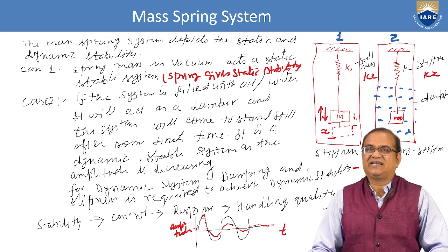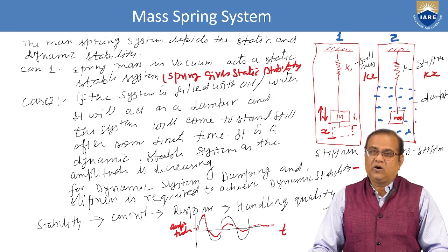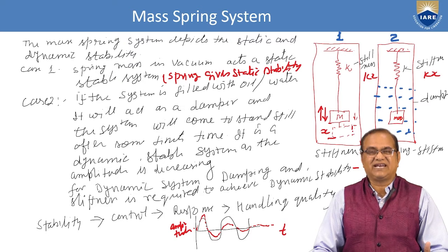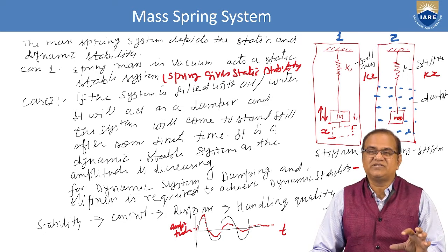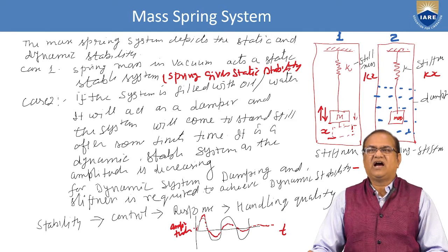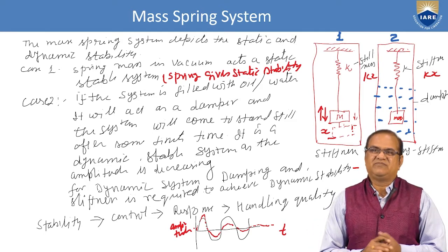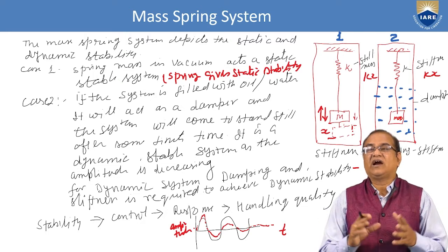First we have to understand the stability, which is static stability and dynamic stability. Then we have to see the effect of the control, and after that how much response or how much time it takes to come to its equilibrium, and then how smooth the aircraft is, meaning how nicely the aircraft is controllable.